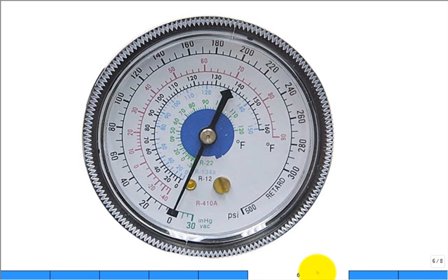Anyway, careful. If you get one of these gauges, they basically give you the PT diagram in the face of the gauge. The outer is the pressure in PSI starting at 0, 20, 40, going around. But if you know the pressure and you know what refrigerant you're measuring, oh, you're measuring 410A. If you're out at 60, then the temperature is in degrees, where is it listed?